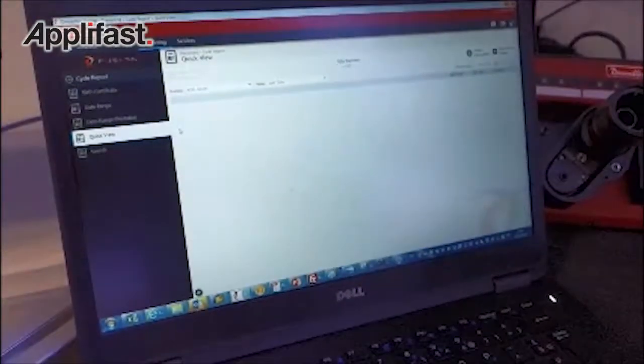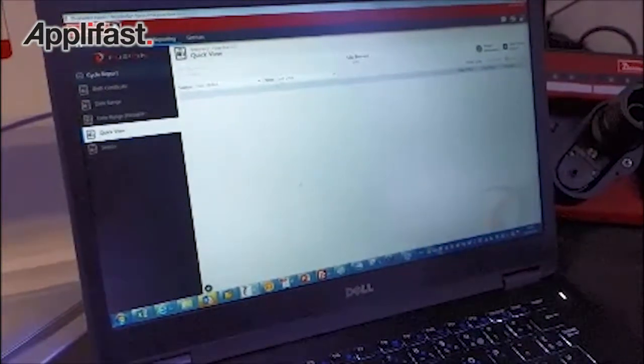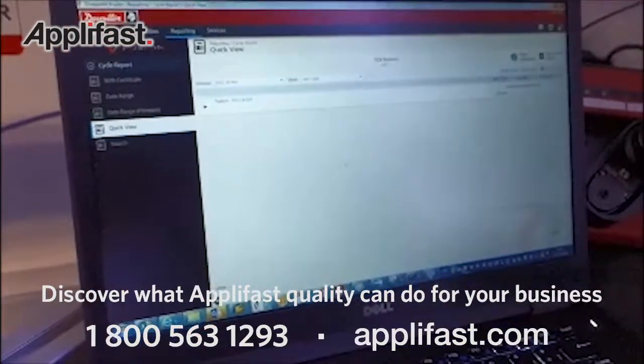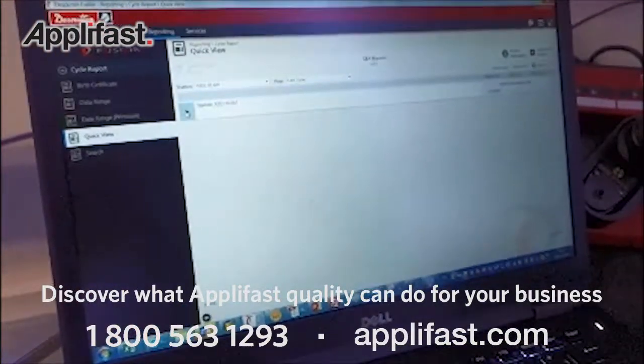As you will see, with the Pivot software you will get full traceability. I go for quick view, last cycle, short cycles. Then my system is linked to a database, and I can retrieve exactly the different information for each one of the steps of the process: the outcome, the time, and potentially the operator that has done it. So this is how we finalize and close the loop with full traceability on each one of the steps of the operations. So that's some examples of Industry 4.0, the smart factory, with the Desoutter tools and process control.